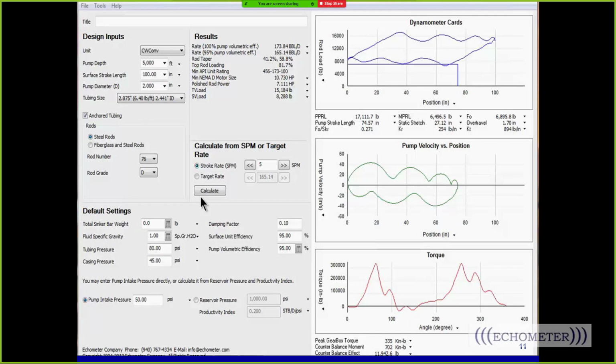You know, the NEMA B motor that really isn't designed for cyclic loading tends to be stiffer and not slow down. And so when you use a NEMA B motor on a rod pump system, you tend to get higher current draw, and you'll have to use at least 1 to 2 sizes larger motor than what QRod will predict. A NEMA D motor slows down when you have the crank arm at 90 or 270 when the torque is high, and that reduces the current flow and it prevents thermal loading of the motor. So yeah, it probably would be reasonable for a gas engine.